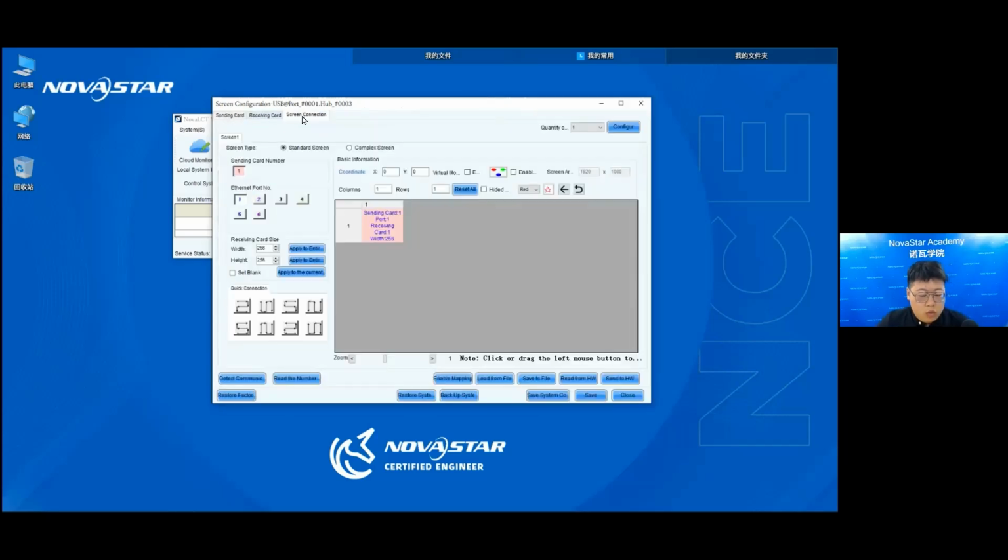Because now the LED screen in my left hand only has 4 cabinets, and each cabinet is already configured, so we come to the screen connection directly. We set only one screen, so the quantity will be 1, and only one screen and one sending card.